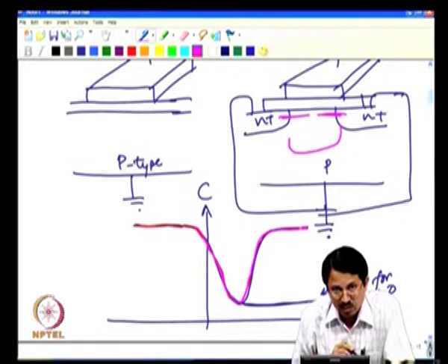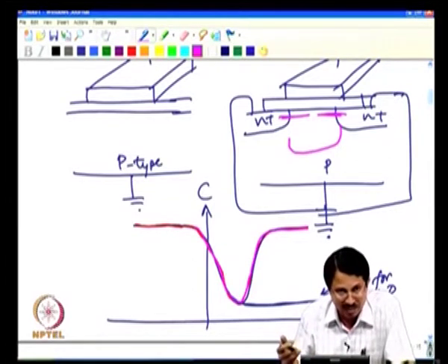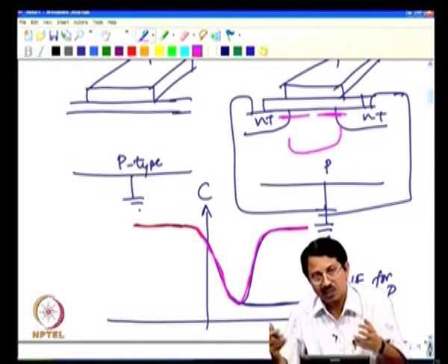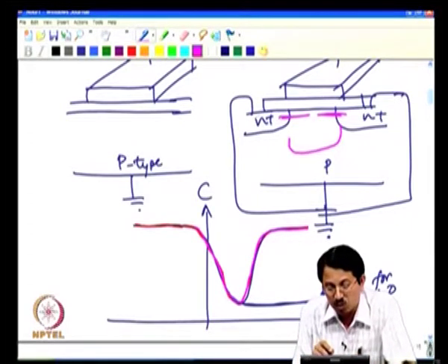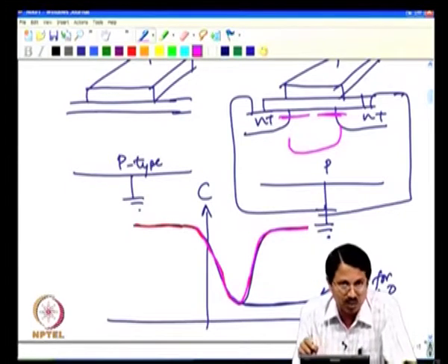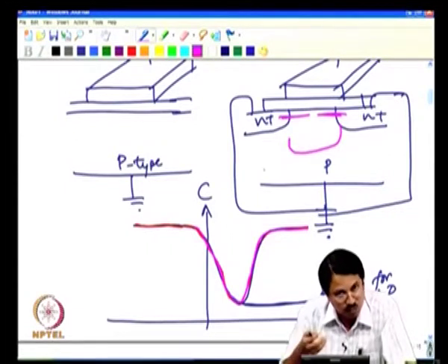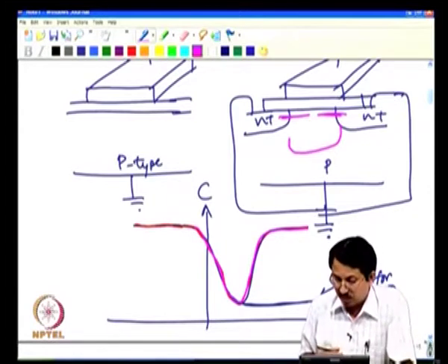This is another important point that you need to recognize: that is why we make these junctions, right. So that instantaneously we can turn on and turn off this transistor. Otherwise, you would not turn on the transistor at terahertz frequency if you have to wait for these electrons to generate. Because we have this source, so called source junction, but here both are source junctions because both are at ground potential. But in the transistor action, one of them is at positive potential, that cannot source because you are draining the electrons there, but the source can instantaneously supply electrons into it, right, and that is how we can switch the transistor at very high frequency.